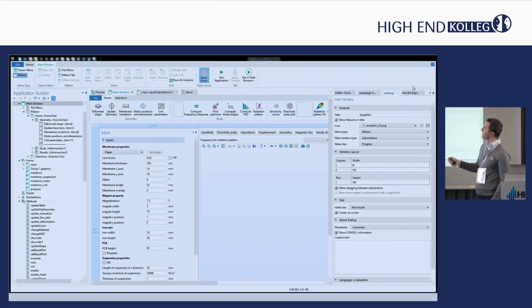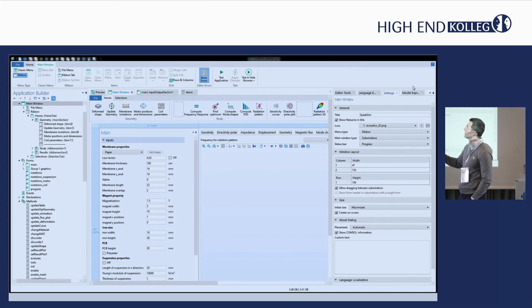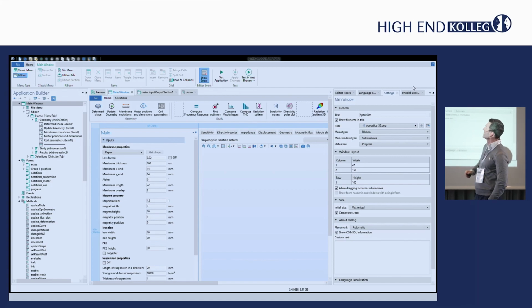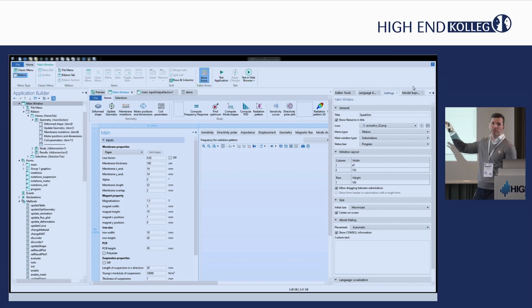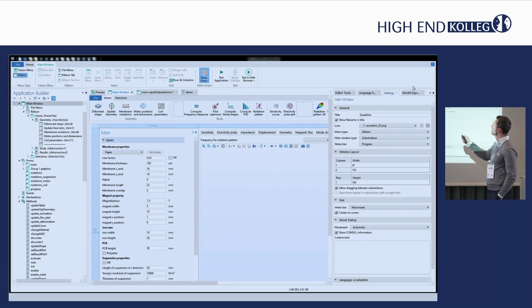So that's the basic idea, and that's the simplified version. That's the application builder, so a custom graphical user interface can be used. Here at the top, all the buttons are available. That was in the requirements: to build the geometry, calculate the frequency response. There is some sort of optimization inside to find an optimal shape, to get a flat response. And you can calculate the distortion, the radiation pattern, and then there is a results section, with certain buttons for certain plots: sensitivity, directivity, the radiation pattern in 3D, and here we have many of those graphical figures that can be used there.